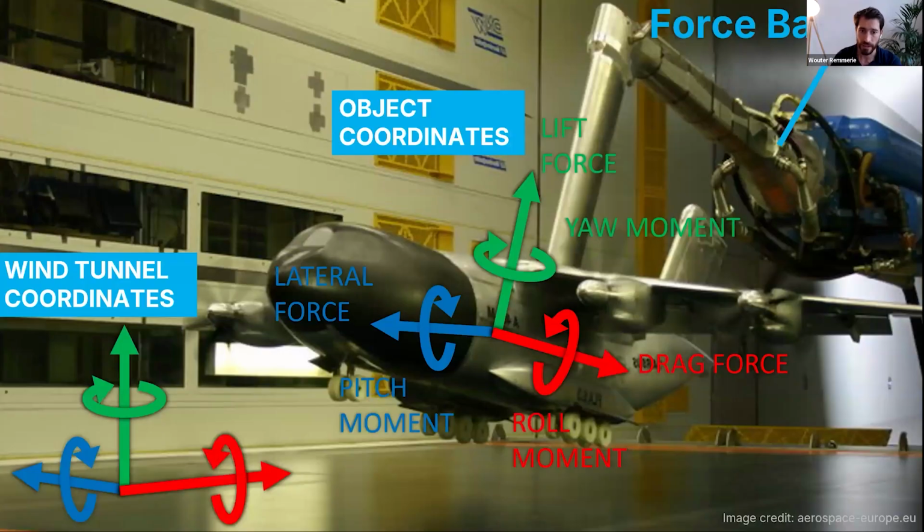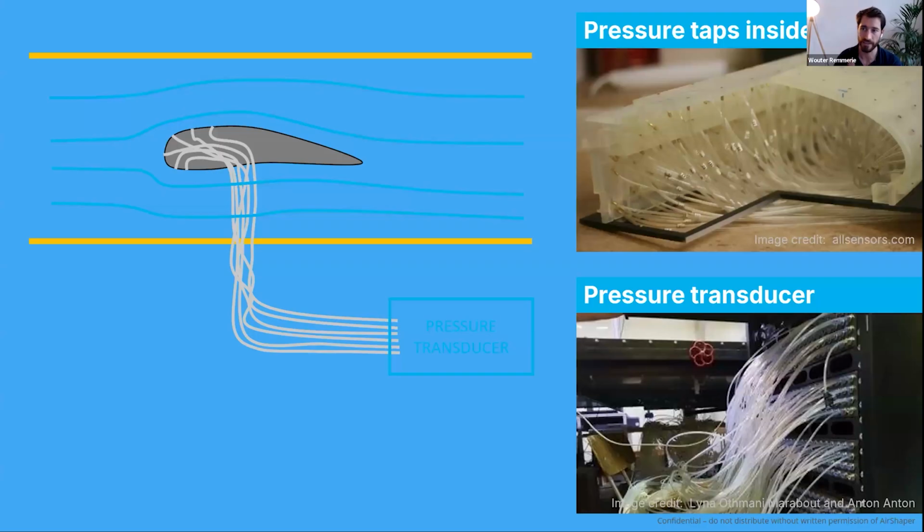And you need to measure things. In the virtual world, with simulations, it's easy to measure things. You can ask your data, please give me the total force, or please give me a slice of the velocity. In wind tunnels, you need special equipment to hold your object, to measure the forces, the moments, and so on. Nevertheless, it can be done and it can be very, very accurate. And we still recommend wind tunnels. I mean, as a final validation, in every single report that we run, we still say, please do execute a wind tunnel test because that is your most definitive validation.